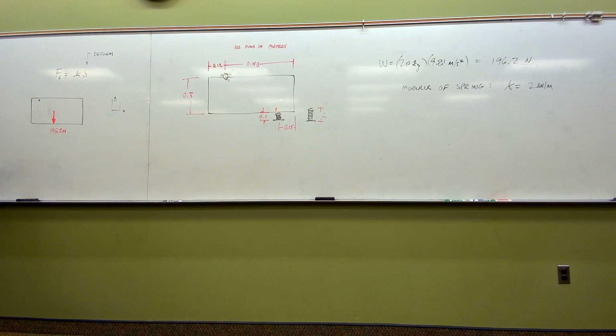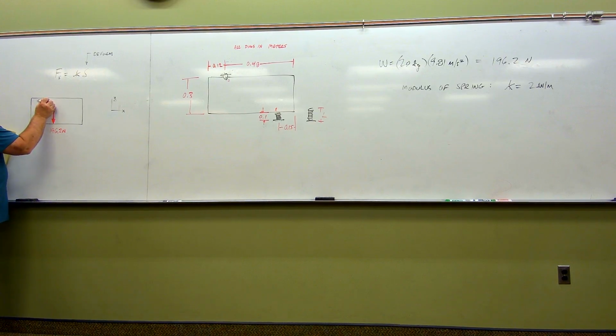2-force members have no weight. This thing does have a weight, so we can't make any simplifications on that. We kind of check the box, not a 2-force member, and go on from there. So therefore, up here, I do have some arbitrary X force and some arbitrary Y force. I don't really know the directionality of these things. It doesn't matter. So OY, OX, I'm good.